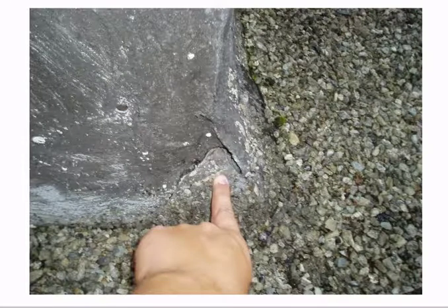Next, Craig, we're seeing this all the time where this is a corner flashing that's clearly cracked and open. A lot of these corners, they'll take a lot of abuse because this is from other contractors, and sometimes other contractors don't really take care of our roofs. They have no respect for the roofing system. If it's a mechanical contractor, some sort of equipment contractor, they're treating the roof system as a working surface, which I get. They're not trained roofers. So what we'll see a lot of times is they have equipment that's tied off to these corners or curbs, and it's just creating a lot of problems.